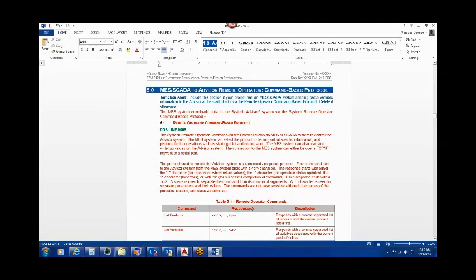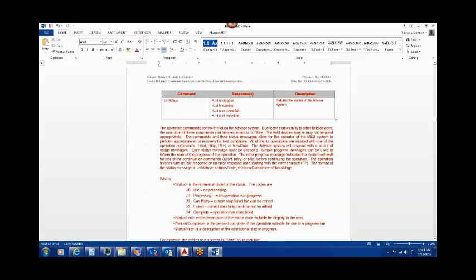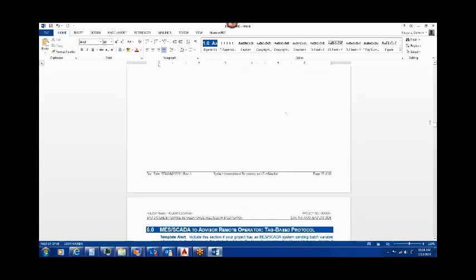We go over any sort of TIPS remote. If you're familiar with TIPS remote, this is a functionality that we provide that allows an external system, like an MES system, to select a product and send us batch variable information remotely. So someone doesn't have to go on the advisor and pick a product manually and enter the information. We provide all of the functionality and interface details as to how that works in this document.